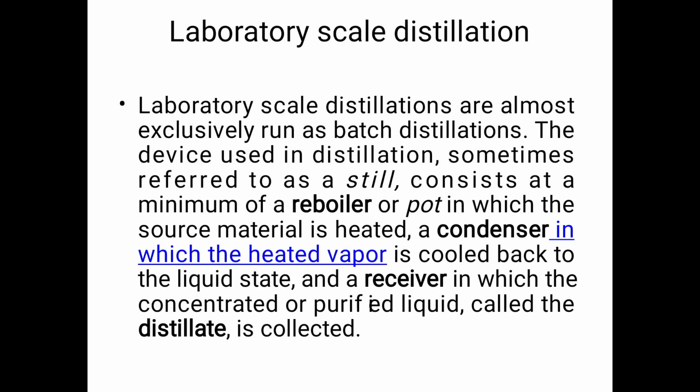Next, we move to laboratory scale distillation. The laboratory scale distillation is almost exclusively run as a batch distillation. I already told that there is a batch distillation process. The device used in distillation, sometimes referred to as a still, consists at a minimum of a reboiler or pot in which the source material is heated, a condenser in which the heated vapor is cooled back to the liquid state, and a receiver in which the concentrated or purified liquid, called the distillate, is collected.